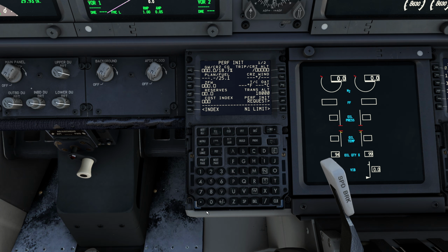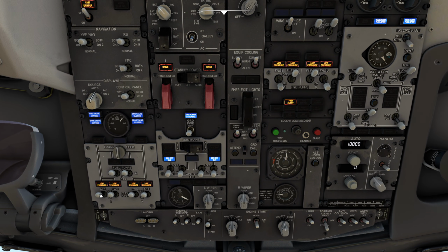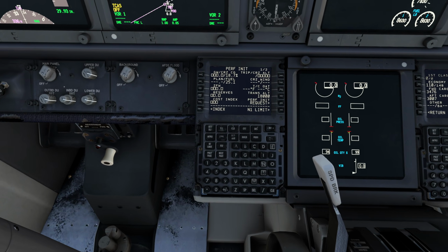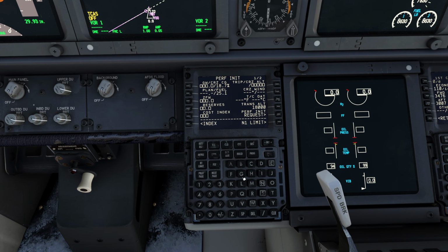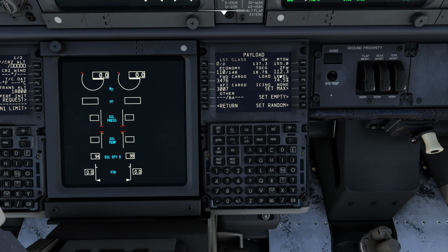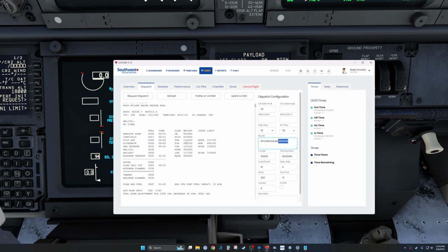It's pretty hot outside today, so they're probably getting pretty toasty in the cabin right now. So what we're going to do first is turn on the left aft fuel pump, and then we're going to go to, actually before we do that, I forgot to load fuel into the aircraft, so let's do that real quick. Let's come over here, and we can use this FMC over here. So let's verify. Zero fuel weight shows 112.3. Let's make sure that that's correct. That is what we're supposed to be flying. 112.4, that's good. It's close enough.